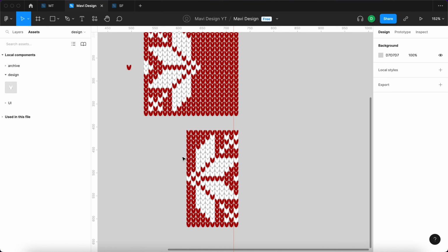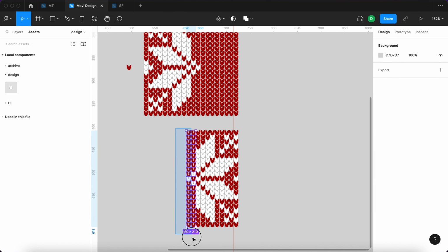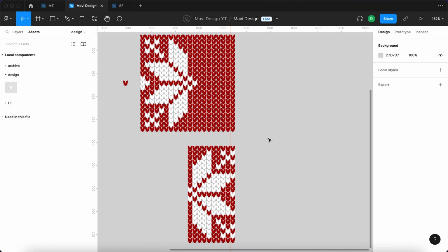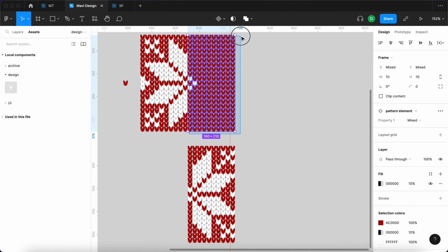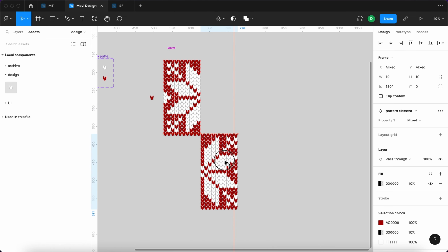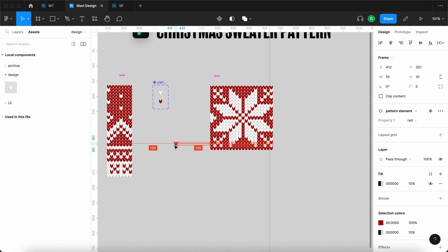Now what I'm going to do here is remove just 1 leftmost column from this group of units. Remove this one, and then what I'm gonna do is remove all these columns where they will overlap with this group, right? So right here, select all these and remove that. And then finally, we can take this group and move it over here like this to finalize nicely this second pattern. That would be the second pattern.